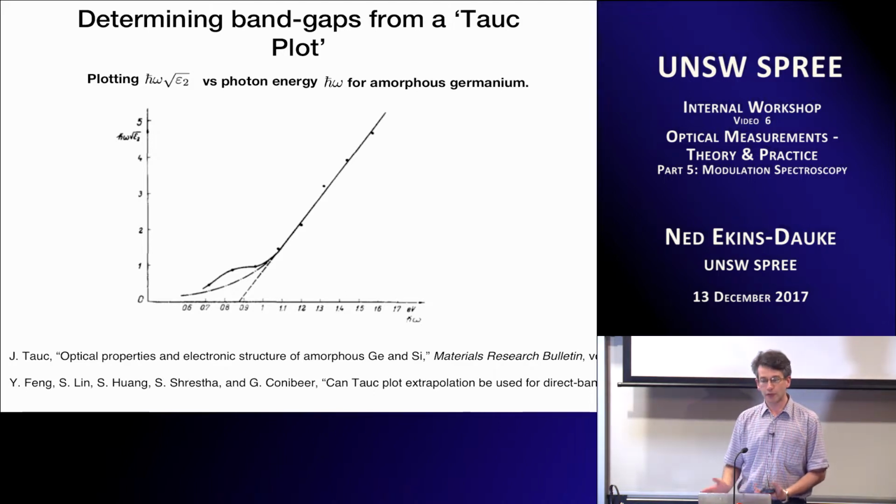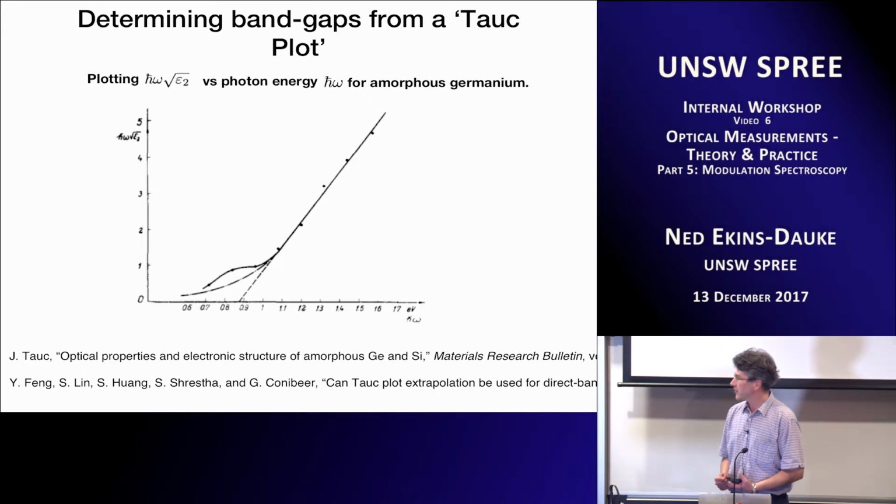As a graphical construction, this works, but as was pointed out by some of our colleagues a year or 2 ago, and unfortunately the reference has gone off the screen, I apologize for that, it only works in three-dimensional semiconductors. If you're looking at nanocrystals or something, you can't expect to be able to make this plot and get a reliable indication of the band gap.